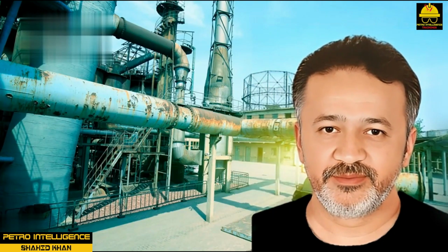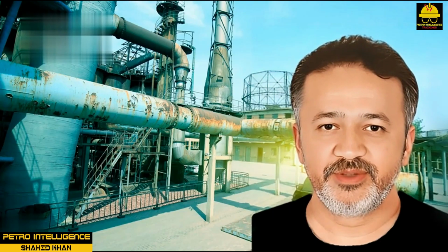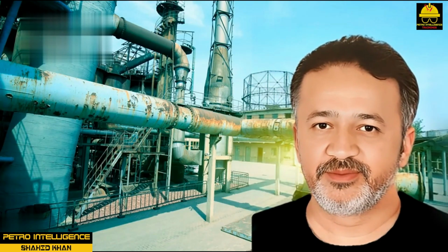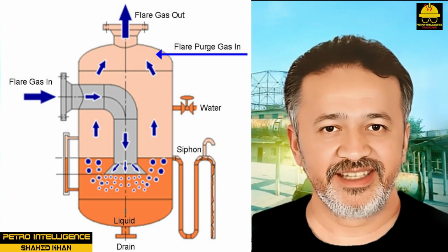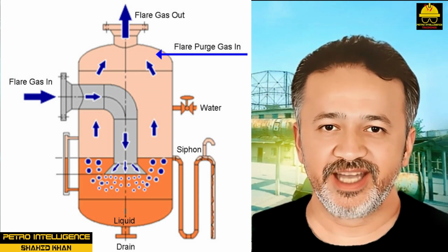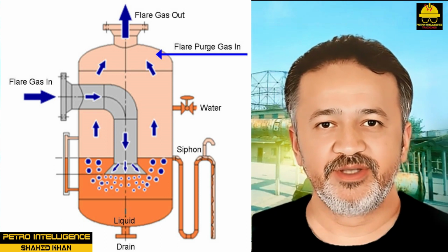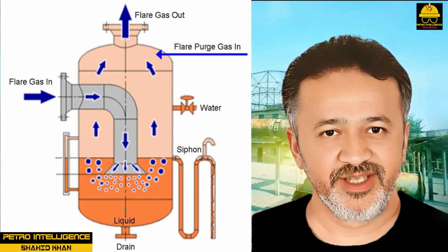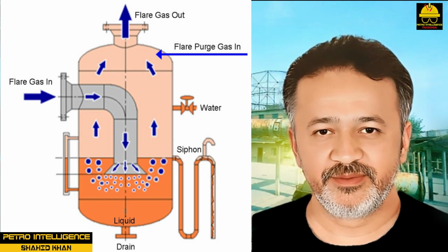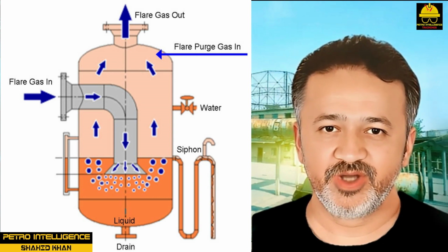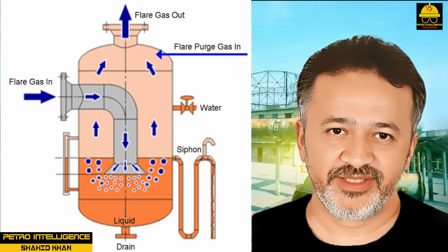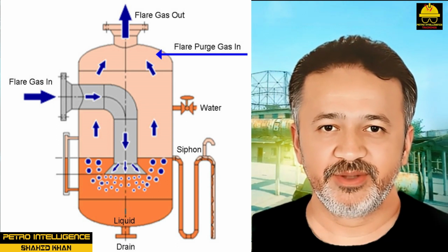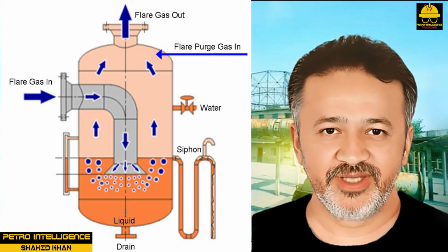Flare systems. Flare seal drum function. A nitrogen purge is maintained on the flare headers to avoid explosive mixtures in the flare lines. Nitrogen and natural gas connections are provided at the end of the header. Normally, the flare system is operated with a water seal in the flare knockout drum. This water seal ensures a positive pressure on the flare when it is necessary to access equipment connected to the flare for any reason. An analyzer continuously monitors the flare at the stack for oxygen.